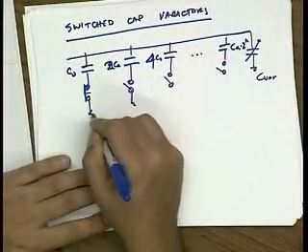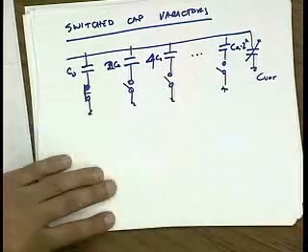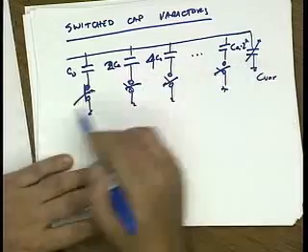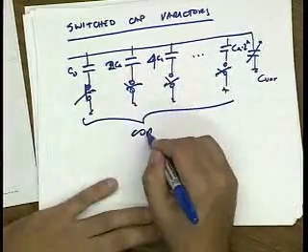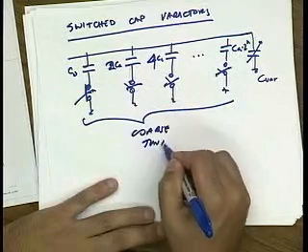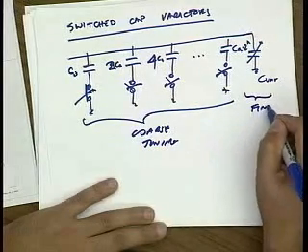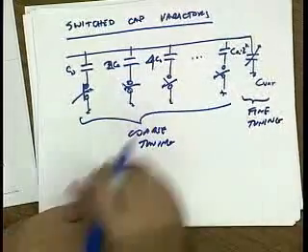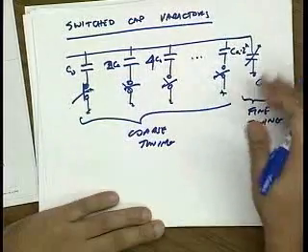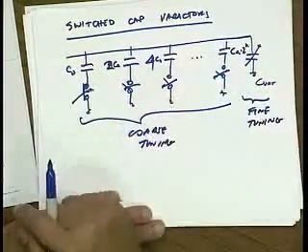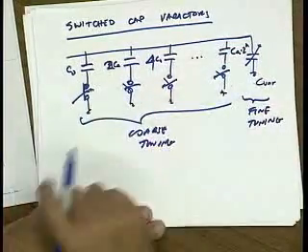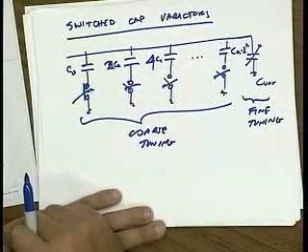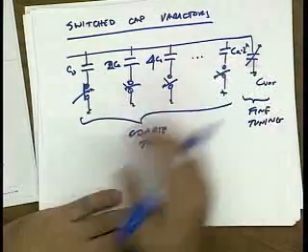And I can just ground these, for instance. Or I could have a differential version. So by turning on and off different switches here, I have a coarse tuning. And I have a fine tuning. Now, in Al's project, he talked about something similar to this, except he got rid of the fine tuning. He was able to get enough frequency resolution just using the digital tuning mechanism. But you have this flexibility. You can actually use both.